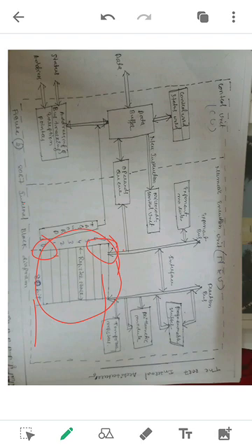The 8087 converts the number from memory to 80-bit temporary real format, and it decrements the stack pointer to 111, and writes the temporary real number to 111, and that is nothing but register 7.